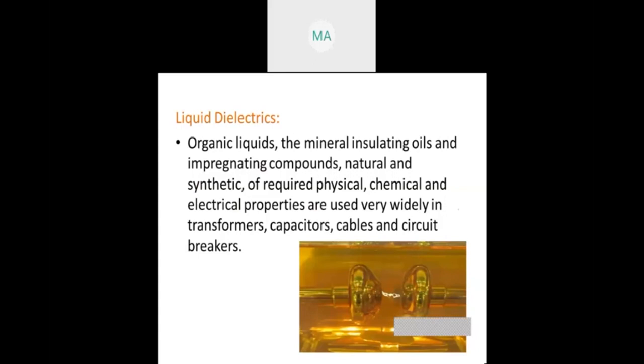Here is a vacuum circuit breaker, how it will be. It is enclosed, and whatever gas is there is extracted through vacuum devices, and whenever a fault occurs, the arc is extinguished in that vacuum.